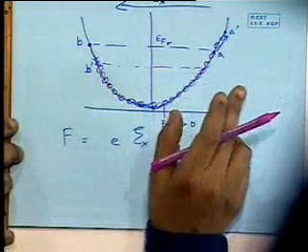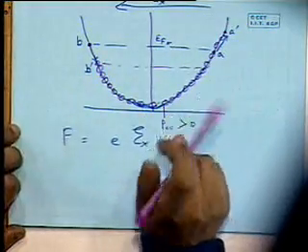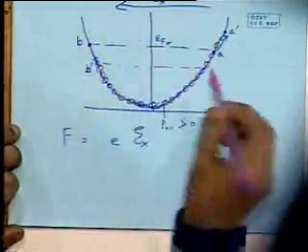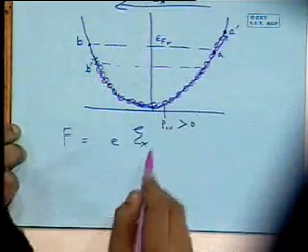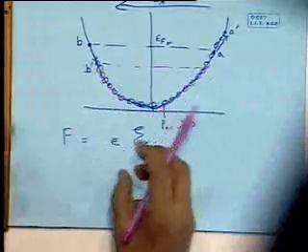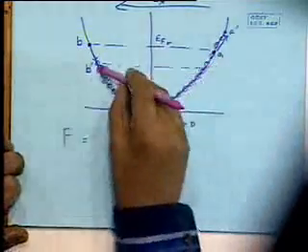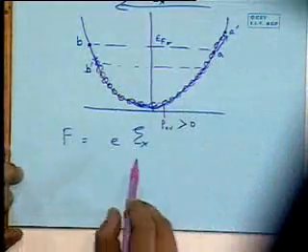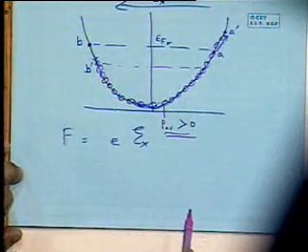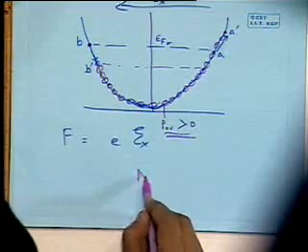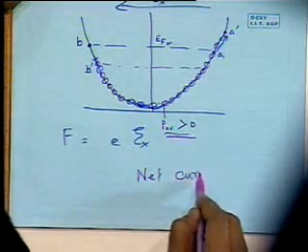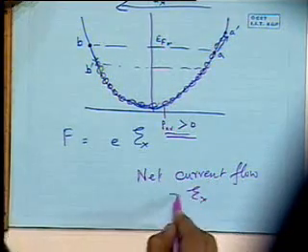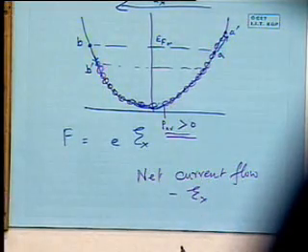So this translates to current flow in which direction? Along this side. Electrons moving that way means current flowing in this way. So because of this change in their average momentum, and as you can see, everything below this is cancelling each other, but above it is moving in some net direction. We have an average momentum that is greater than 0, and so we get current flow in direction of the field, which is minus Ex. Okay?